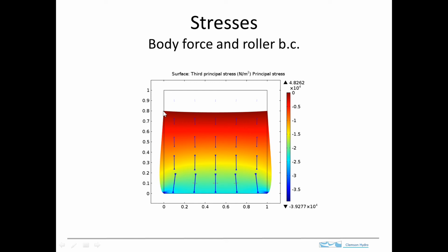There's no bulging up here at the top because this all is from the load is from the weight of the material. So in this deformed view, this is the top of the surface, and so there's no load here. The load increases with depth, and we have this outward bulge. We also just have this subsidence, or this downward displacement from the weight of the material.